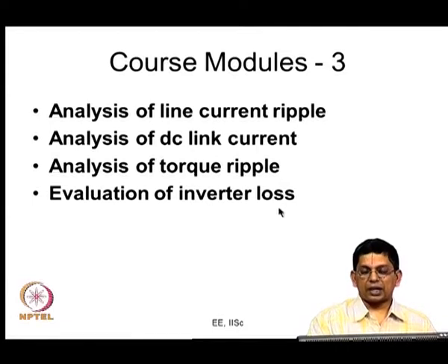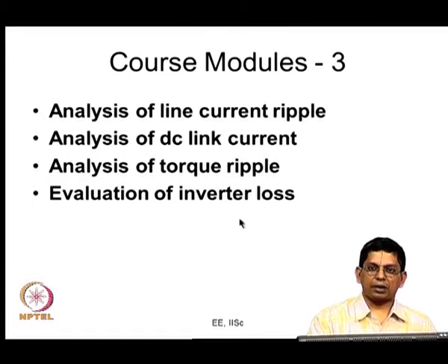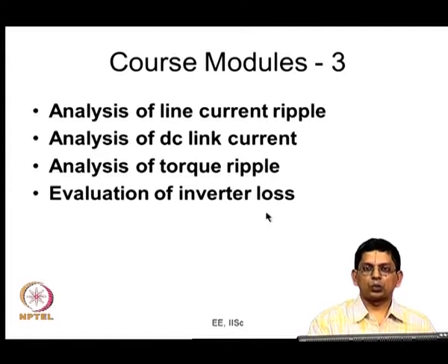On the other hand, for the switching loss, whenever an inverter switches, if it is a 2 level inverter, the switch is going to be switching a voltage of VDC, whereas as we will see here, it will be switching only a voltage of VDC by 2, and therefore the switching energy loss could actually be lower. So, when you go to fairly higher switching frequencies, a 3 level inverter might lead to lower switching loss than the 2 level inverter, or the overall power conversion loss can also be lower than what you can actually get with a 2 level inverter.